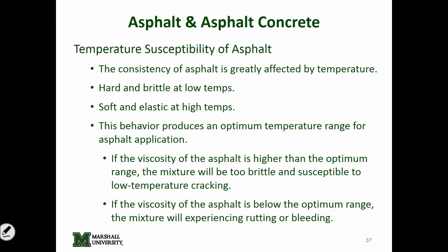Very temperature susceptible, as we all realize. In the summertime, you can feel asphalt getting soft under your feet, right? So it's very temperature susceptible. Therefore, it's very difficult to design with, from the standpoint that you've got to make sure that it can handle both the cold temperature and the hot temperature in the region you're in.